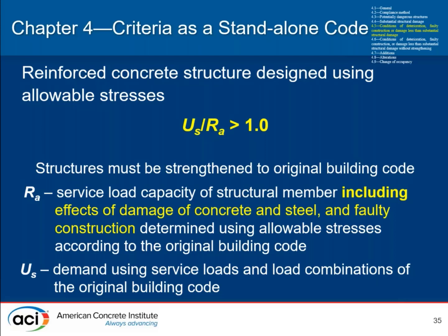If the ratio of service demand to service capacity exceeds 1.0, then you have less than substantial structural damage and you must be strengthening to the original building code.